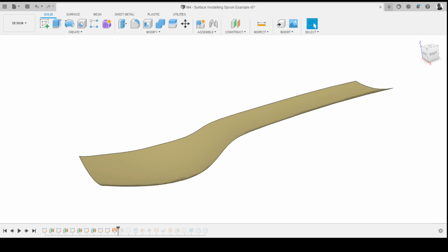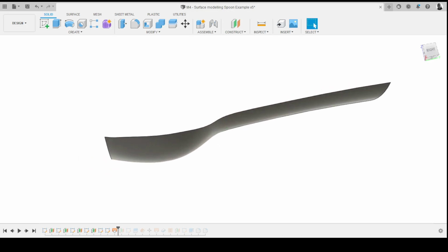What we can do with surface modelling is just model surfaces and then give them a standard thickness, for instance, would be one way of doing it. Another thing that we can do with surfaces is create complex compound curves that overlap, then trim those surfaces back to each other. That's called overbuilding. That's a whole other area of surface modelling, which I'm not going to go into now. I'm just going to show you the basics of surface modelling.